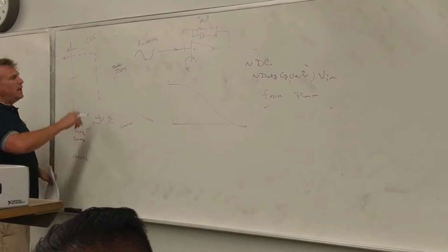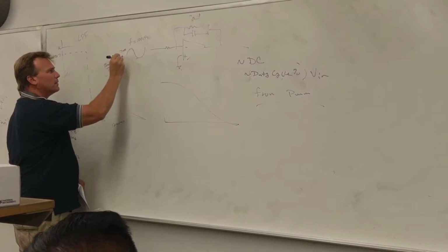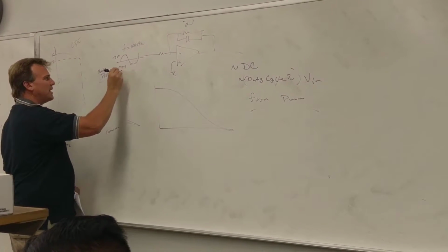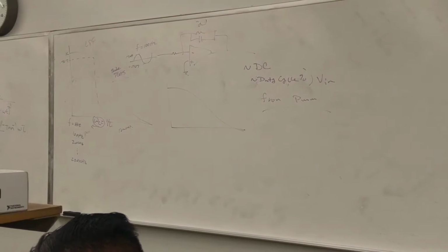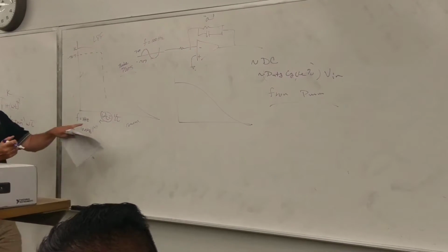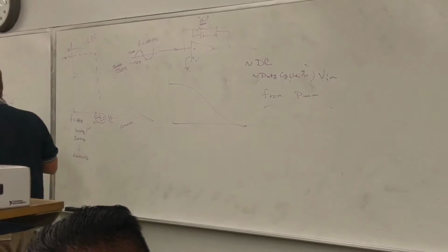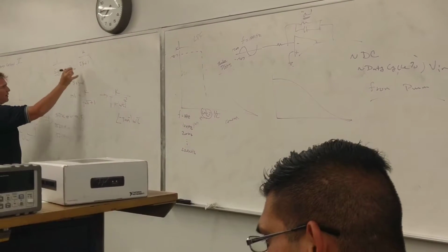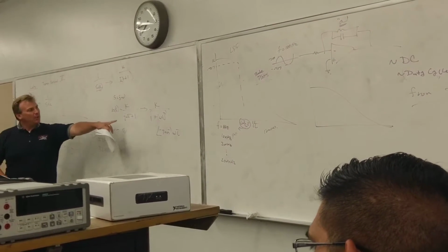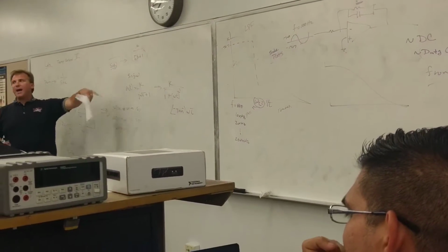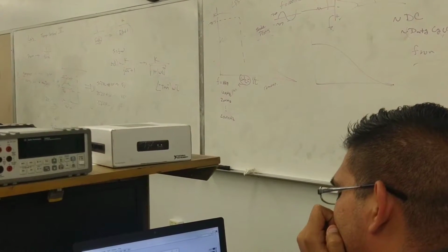The frequency at which that amplitude decreases to 0.707 is omega C. So I can actually find omega C, and therefore I can find A, and through tau as well. Because I know omega C, I can find A, I can find the system's response by sweeping its frequency.